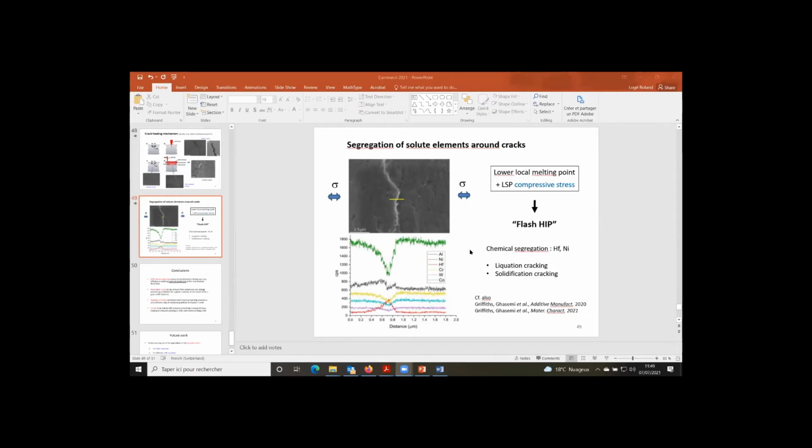Okay, the sound was not very good, so I hope I understood the question. The question is whether, instead of using nanosecond lasers, we could go up to femtosecond lasers to create the shock wave. Yes, there are some indications that these even faster lasers could be used. Now the question is also, what is the size of the beam and what is the penetration depth of the effect that we are looking for? If the beam size is too small, then the shock wave propagates in 3D instead of 2D, and you lose in terms of penetration depth.